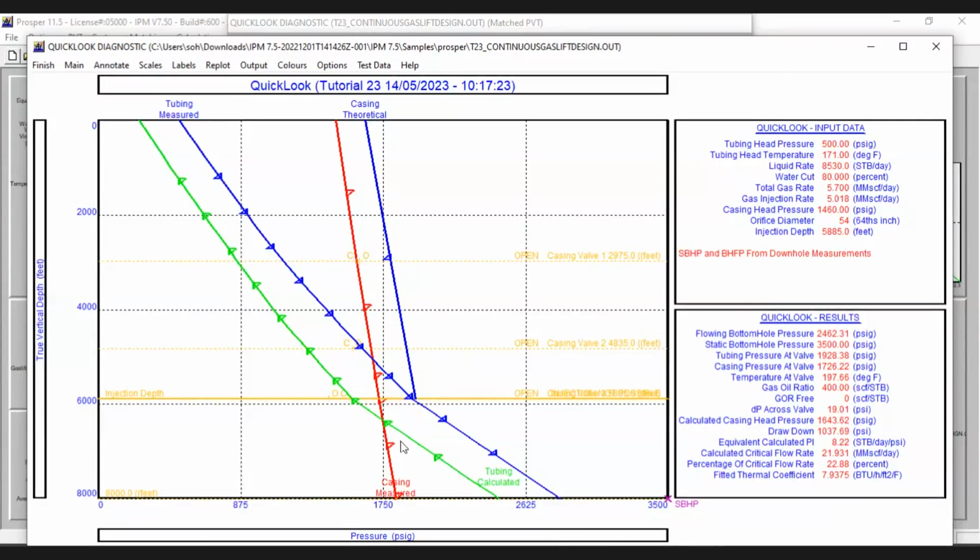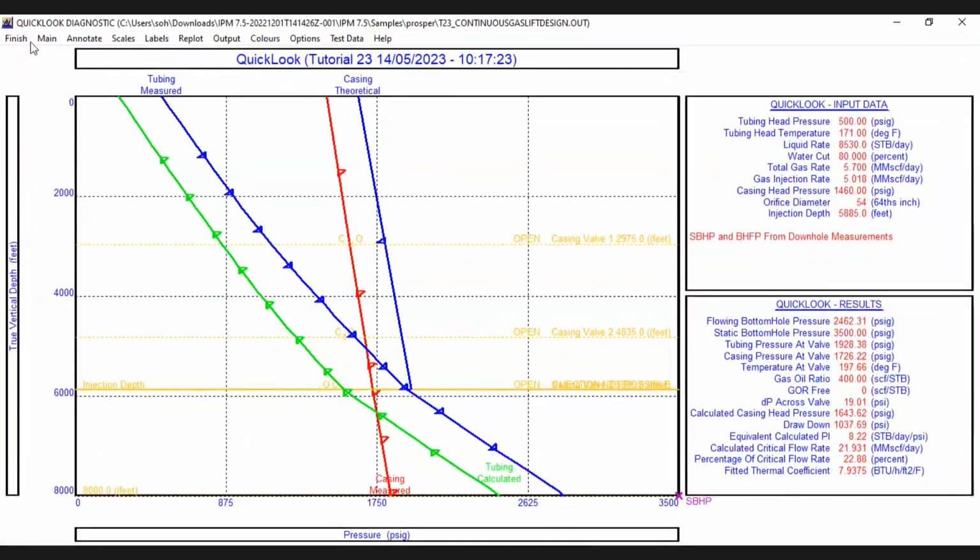So you see, still this item also is not going to affect your case, because from the surface you can read exactly from the choke. Normally in gas lift, you are not installing any surface choke. So that's why the wing valve reading, the gauge, is showing you the surface pressure.